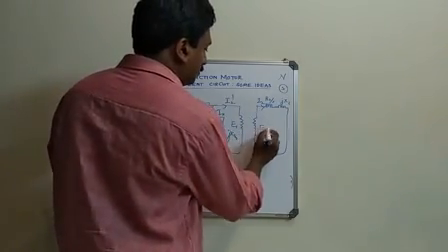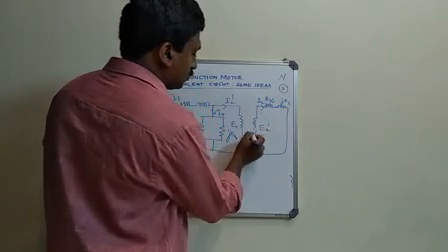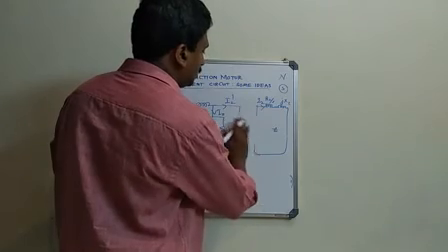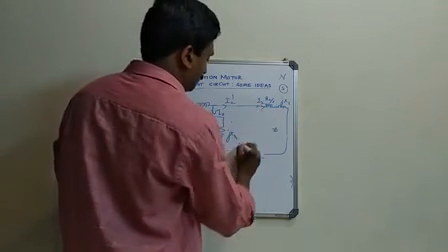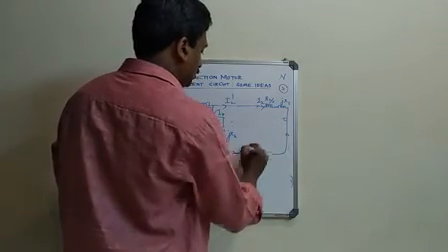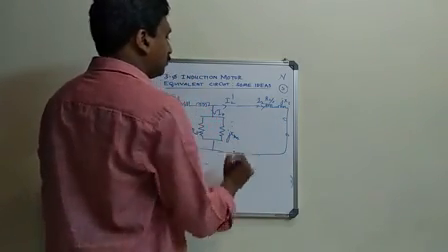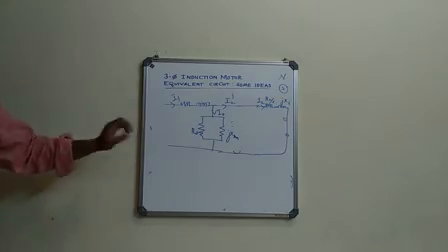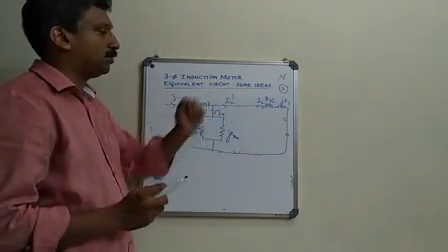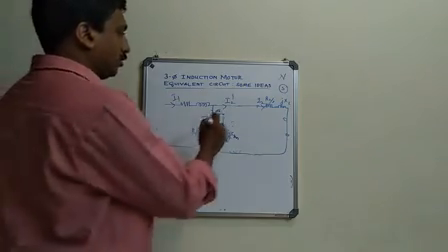So when you transfer this to this side, E2 dash becomes equal to E1. So you remove it and you can do it very simply. So this is the equivalent circuit of the induction motor referred to the stator.